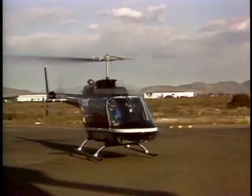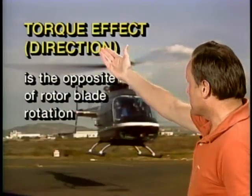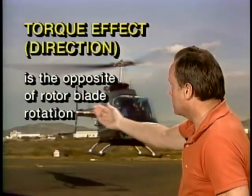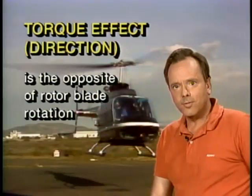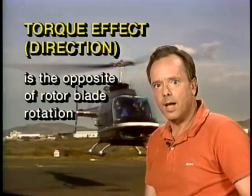Now let's take a look at a few questions the FAA asked about forces on a helicopter. One of those forces they ask you about is torque effect, and they ask what direction it is in. Well, the answer is torque effect is in the opposite direction of rotor blade rotation. Whichever way the rotor blade is going, the torque effect makes the helicopter want to rotate in the opposite direction.